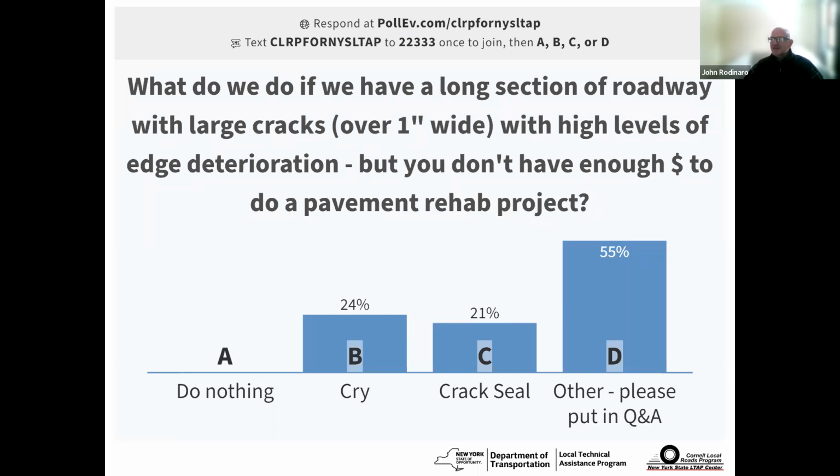I'd have to see the pavement to be sure and know what's going on underneath. Somebody mentioned base repair. I really want to know what the base was. Mastic might work if it's not deteriorated under the base, but the key in all these things is you got to get out there and see what the field conditions are and check the drainage.